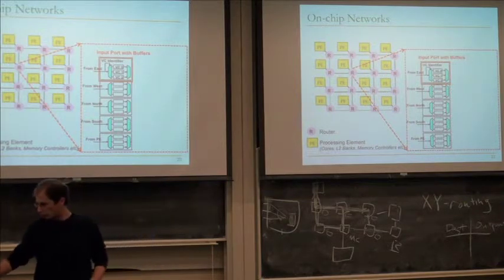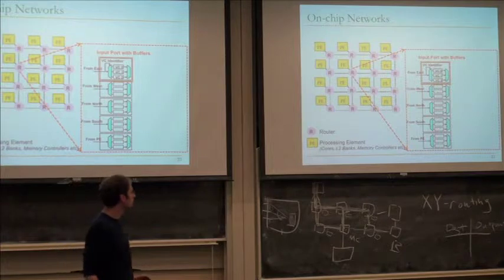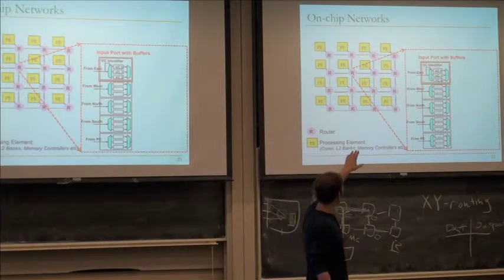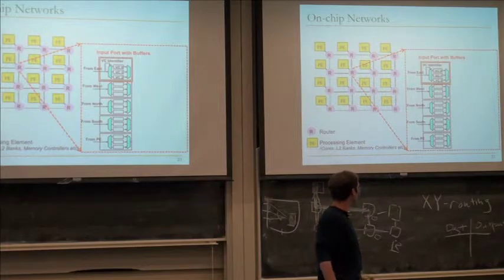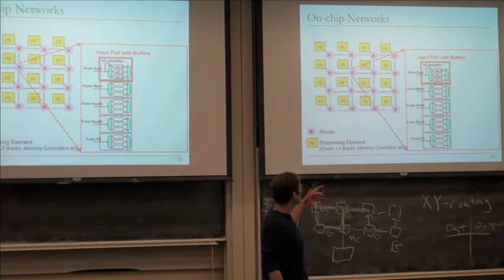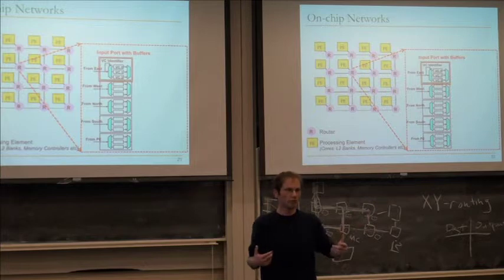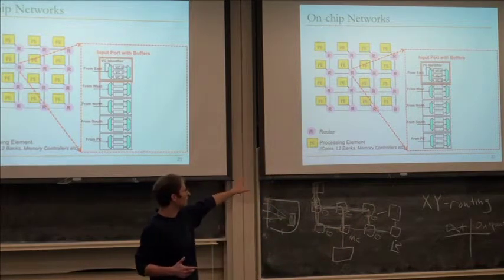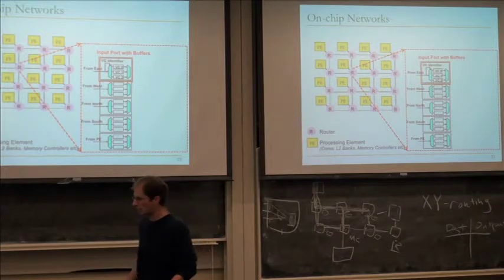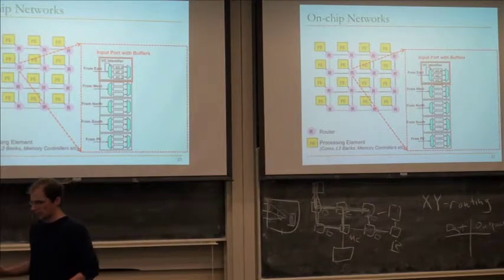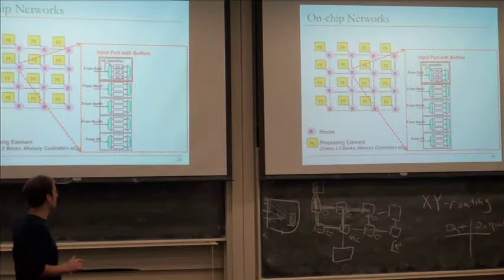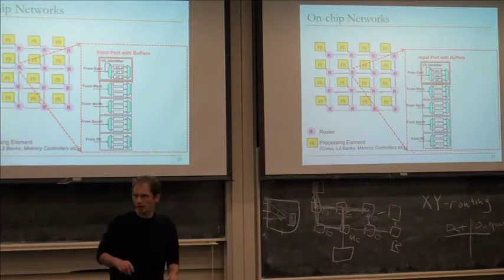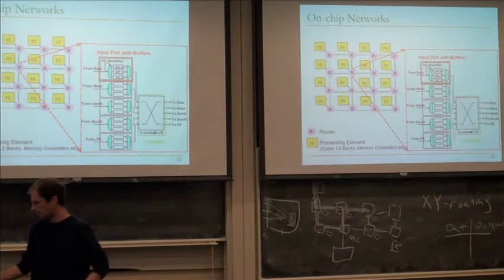And I mentioned virtual channels on Monday. You can design a virtual channel router where the virtual channels are actually separate FIFOs, which is what this figure implies. In that case, you have something like a demultiplexer in front of the FIFOs and a multiplexer behind them. You could also design it such that this is a single SRAM, and then you have virtual FIFOs within it, based on interleaving or address ranges or something. Not really fundamental, but basically you have these buffer structures that are independent at every input.